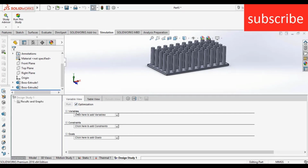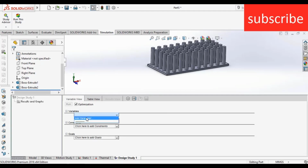The first thing here you see is variables, constraints and goals. Variables are basically those things which I want to change so that I get maximum optimization and a better result. A question arises in your mind: what are the variables in this simulation? Let's see. Click on add variables, click add parameter.